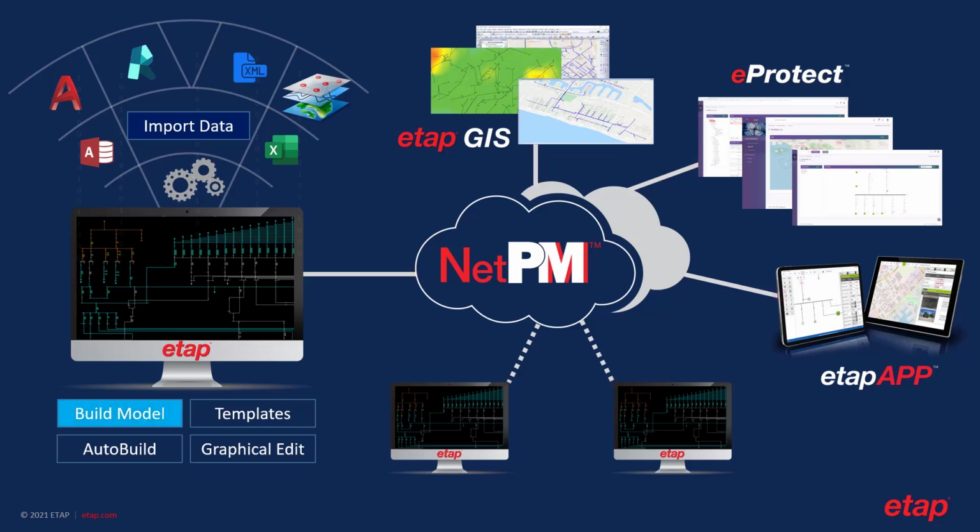Now, the roles are reversed. Whatever information is being broadcasted from ETAP through NetPM to all the other clients that are connected to NetPM, the same information can be sent backwards. So changes made in eProtect, the etapAPP, or other ETAP consoles or workstations are then propagated back to the master, who can continue merging the changes and making sure that all these different parallel tasks that are ongoing, all that information can come together and be put into that one master model.